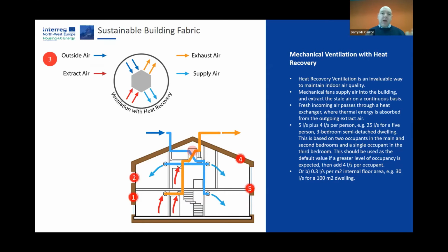For anybody who's not familiar, it draws air from some of the warm rooms in the house, some of the wet rooms where there's perhaps stale air, and those rooms typically have a lot of heat in them. The heat exchanger takes the heat out of that outgoing air, and at the very same time the incoming air gets heated by the outgoing air through the heat exchanger. On both sides it's filtered, so you're getting nice clean air as well. And I've already talked about the CO2 thing as well.